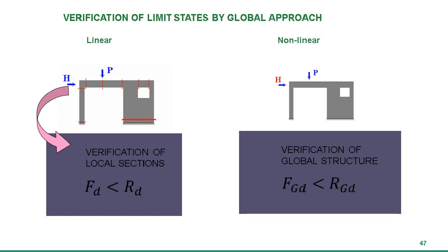And here is a little, let's say, discrepancy: typically we perform linear analysis to calculate the internal forces, but to calculate the strength of our section, we usually assume that concrete is cracked, reinforcement is yielding, so we assume a highly nonlinear behavior. So this is a small discrepancy. On the other hand, it is a simple and very robust and very verified way of working. So if we come to nonlinear analysis, things become a little bit more complicated, and this approach is not so suitable.